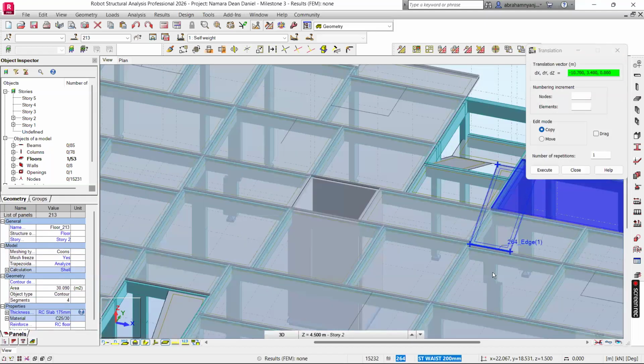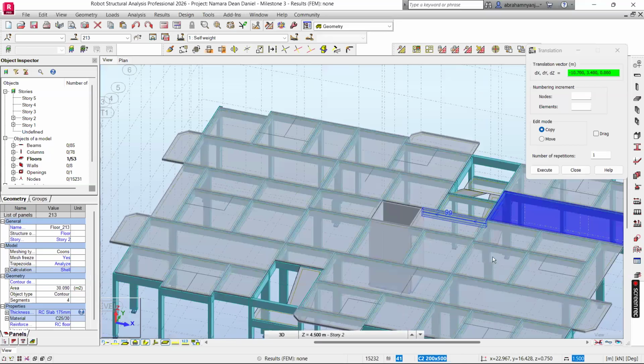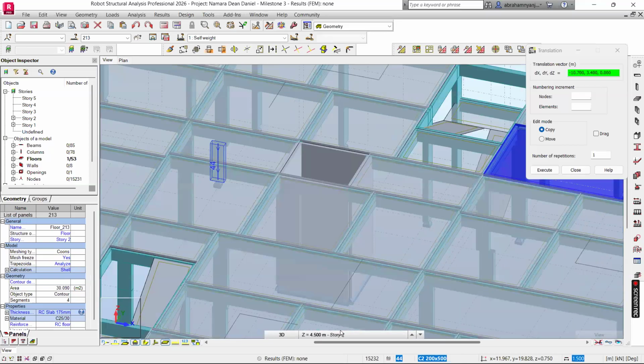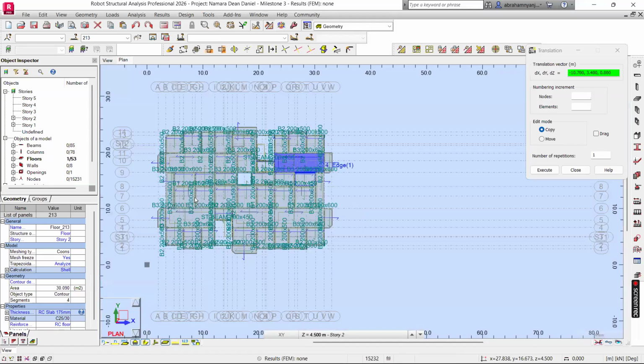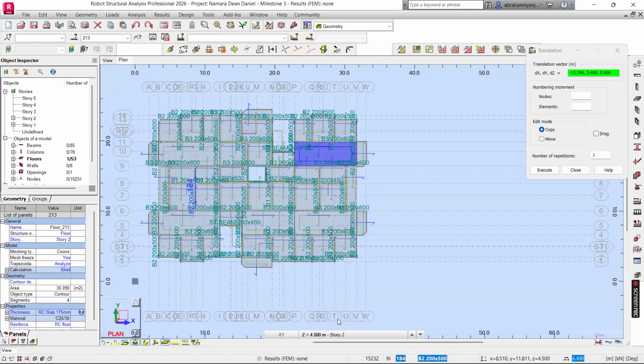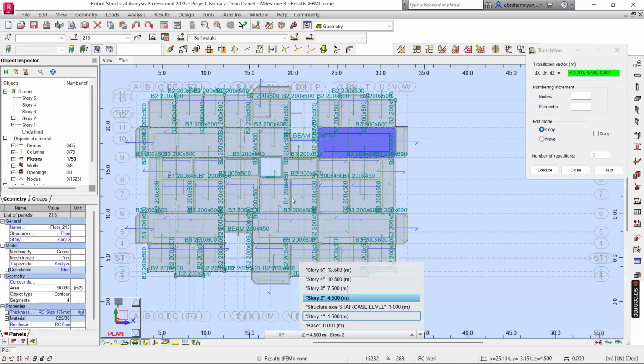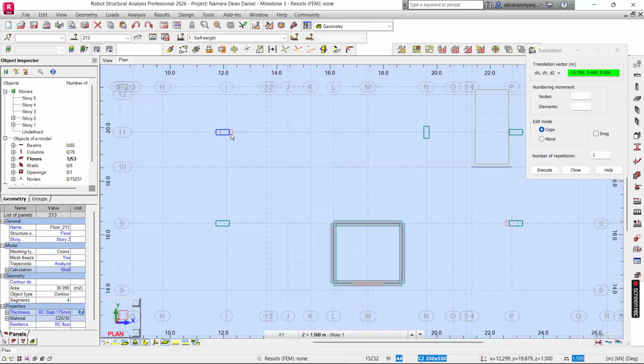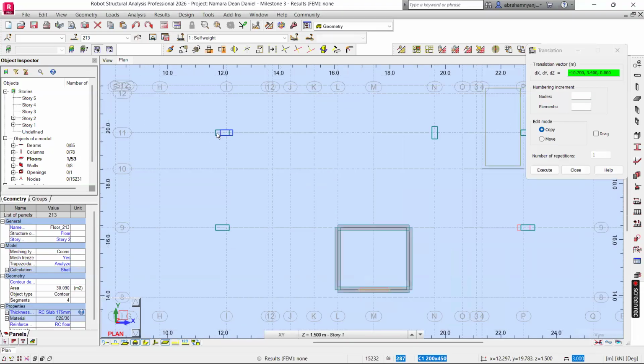But now it looks like your columns down were offset away from this. So I'm going to go to the 1.5. I'm going to go to story 1.5 so that I see, you can see, I think the red columns, those are the ones we have positioned, and these ones are slightly away, the ones that are below.